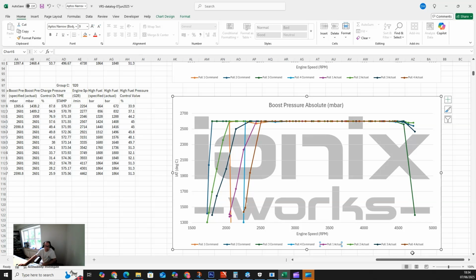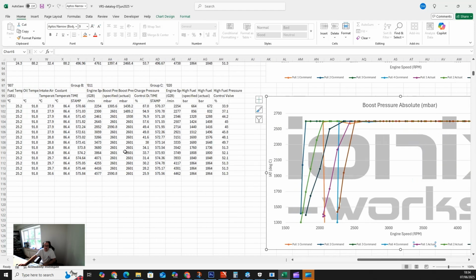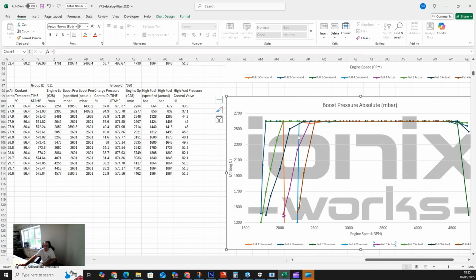So as far as my command in the ECU is going, we're targeting 1.6, but as I say, our sensor is only allowing us to see up to that, so there will be an element of overshoot. We may hit 2700 millibars absolute and even above here. I suppose on that same train of thought, on the undershoot element, if I can maybe zoom in here a bit.